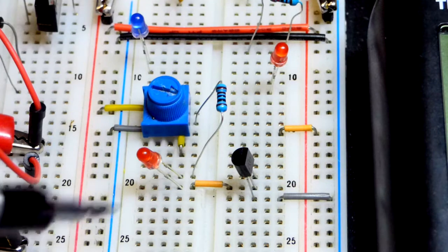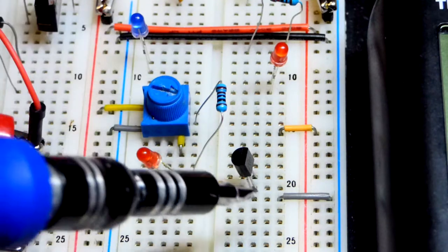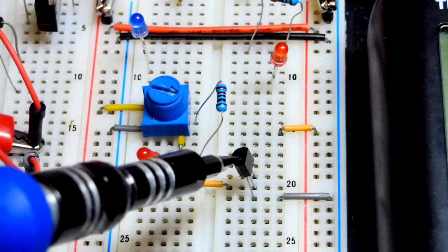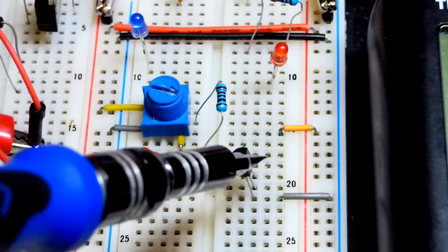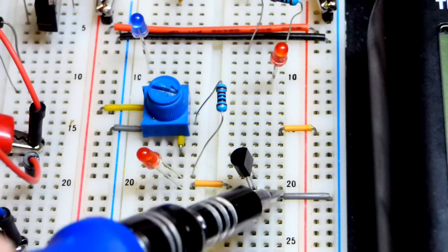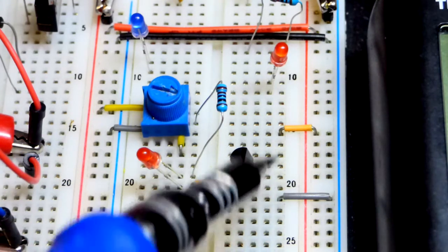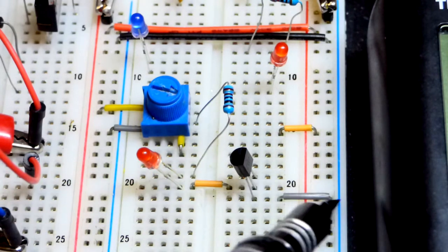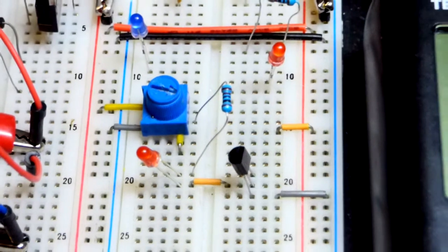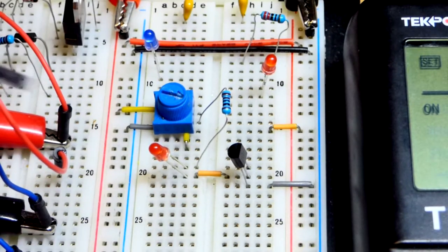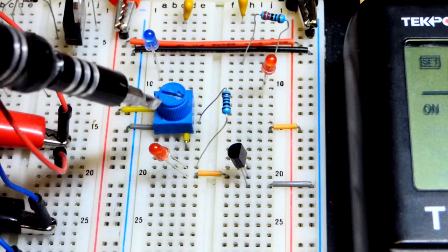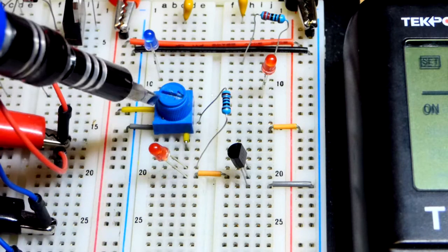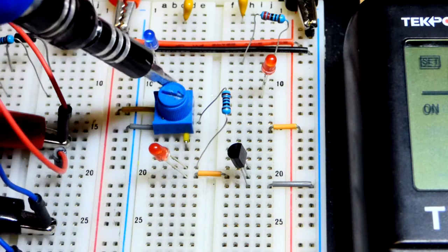Here we have the base part of the circuit all wired up with the NPN bipolar junction transistor. Again, there's the flat edge, so at the bottom is the emitter, middle is the base, and the right pin is the collector. You want the collector towards the positive supply and the emitter to the negative side of the supply with the NPN bipolar junction transistor. Make sure you check out the pins on the data sheet if you are unsure. But in any case, this is a 2N3904.